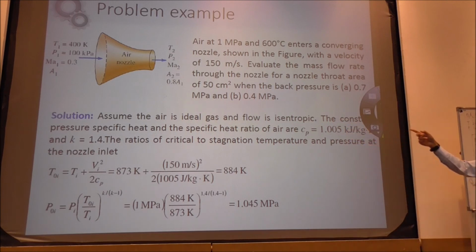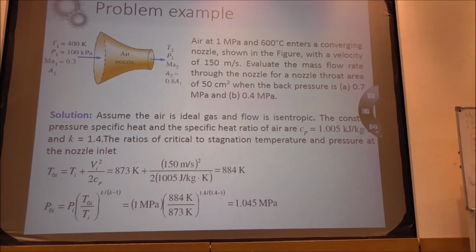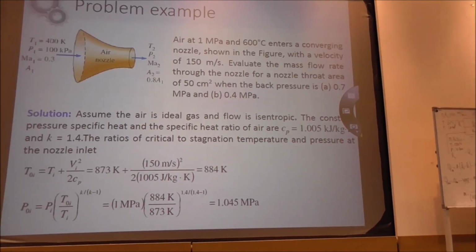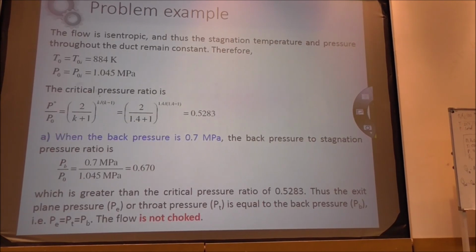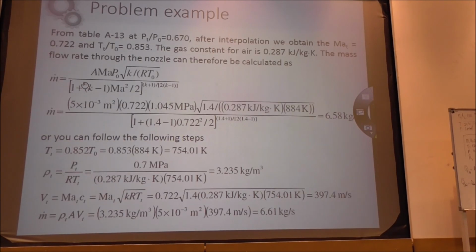It is the total of gauge pressure plus the atmospheric pressure. So when you have this kind of question, those P are the absolute pressure. Remember that. That's why you can use this directly. So those are not the gauge pressure.